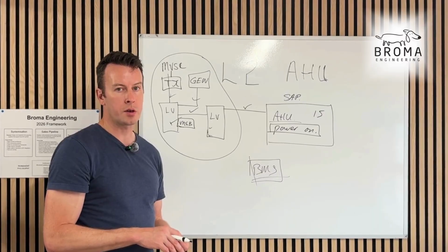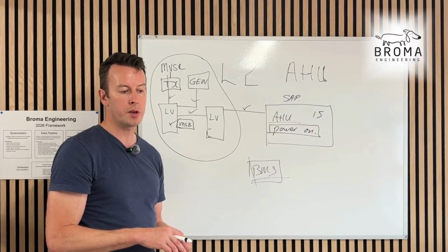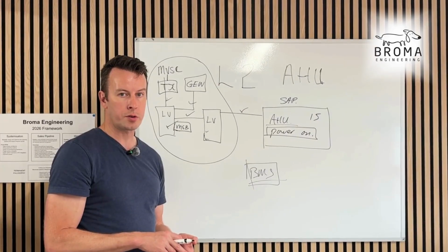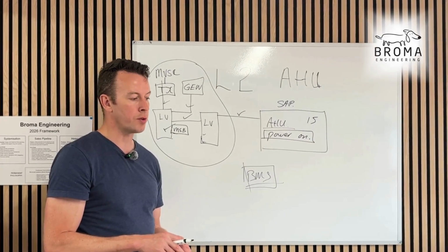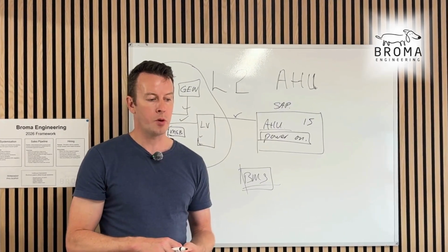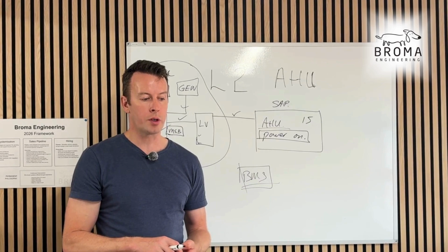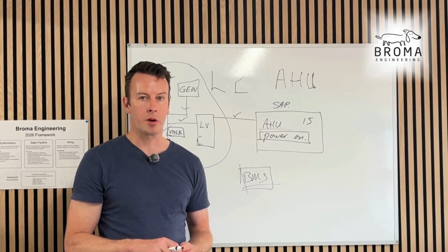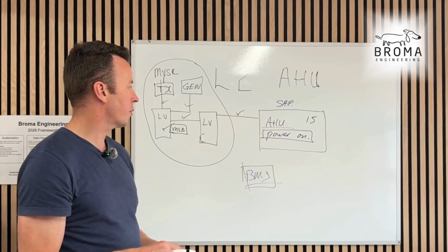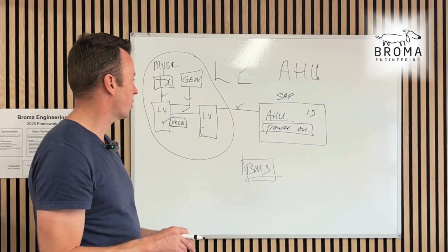Everyone gets together last thing before you leave in the evening and agree that we can do power on in the morning. And then first thing in the morning, operations, whoever needs to be there, engineer of record, CXA, whoever needs to be there is there in the morning. We're ready to take locks off and power it on in a very safe manner. There'll be permit to work as well. You might need a permit to power on. You will need a permit.